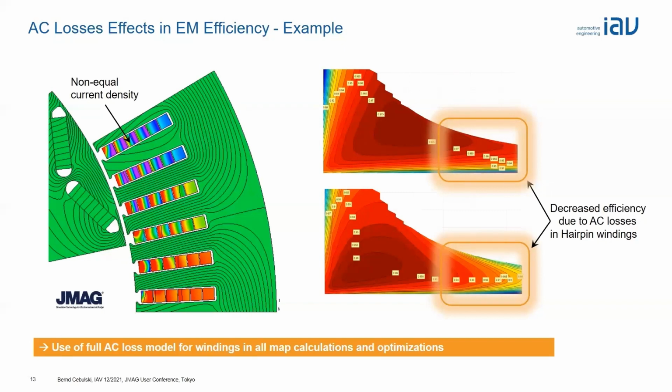In reality, these locations are mixed due to the interconnection of the different slots. You normally have more than one slot per phase. And so you can optimize this phenomenon somehow by placing the bar in different positions of the slot.